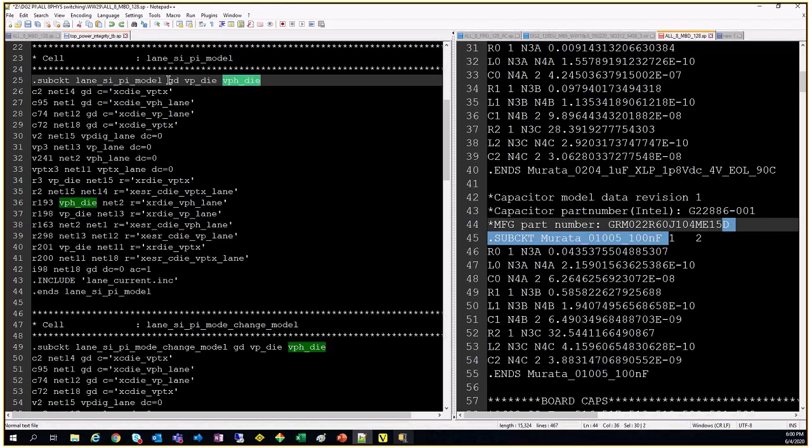If you see here, they named this node as ground. So they're giving you the idea that you should connect your ground port over here. In our case, we don't have a ground port, we don't have any resistor, and we don't have any special ground setting. So we just put 0 there when we're calling this subcircuit.